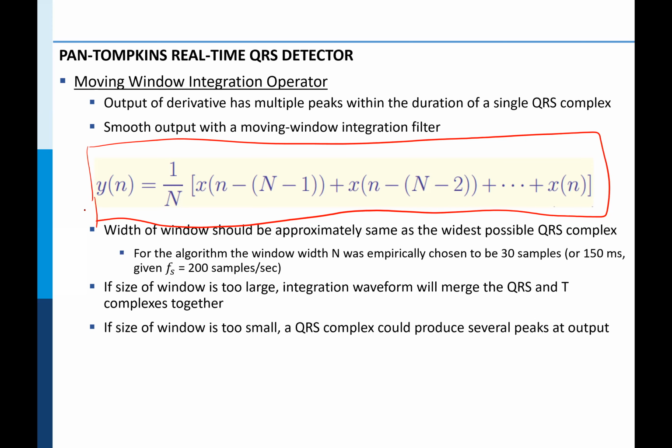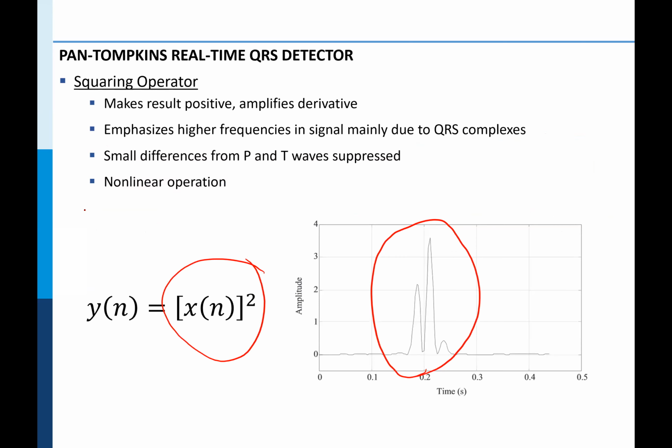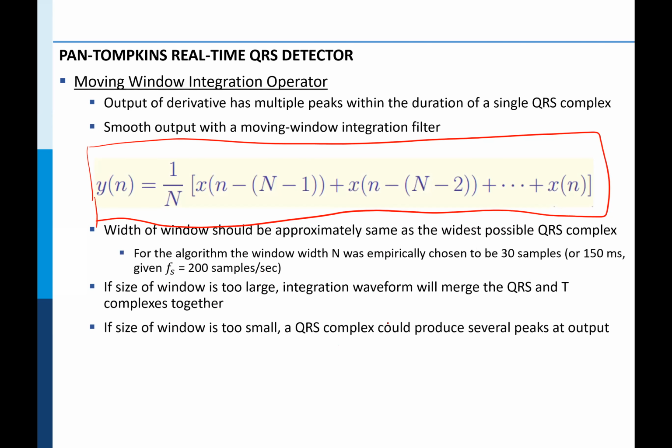Okay, so the examples, the graphs which we have seen before, are cases which are pretty much noiseless, or in other words, they had a very high signal to noise ratio. But in a noisy ECG, it's possible that we might end up having smaller oscillations here. And how we suppress those smaller oscillations is exactly what the moving average filtering is doing. So it's ensuring that such residual high frequency noise is smoothened out through a final stage of moving average or a low pass filtering operation.